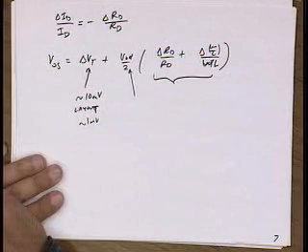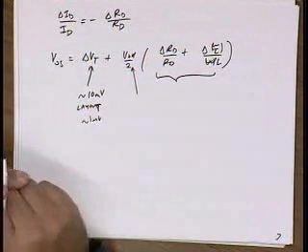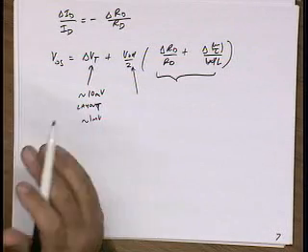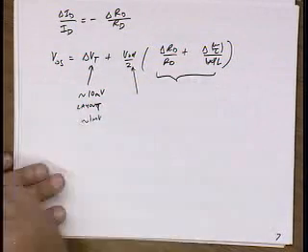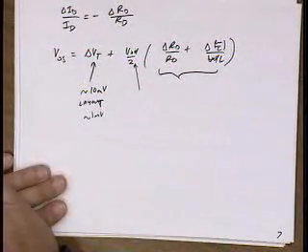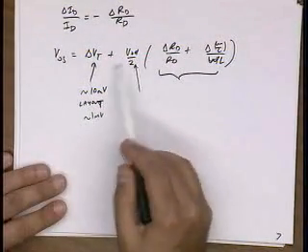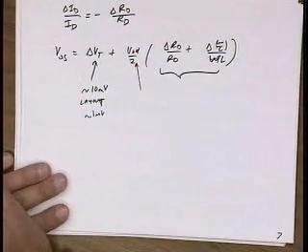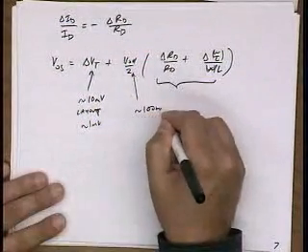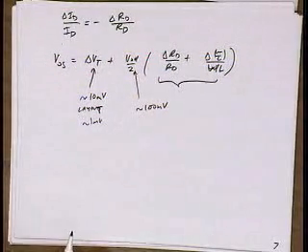How about this term here? Well, unfortunately, by definition, if I'm in strong inversion region, then my overdrive voltage is basically at least 2 to 3 times KT over Q times N, right? So roughly this is at least N times larger than the case of the bipolar. So this is on the order of hundreds of millivolts as opposed to 25 millivolts.